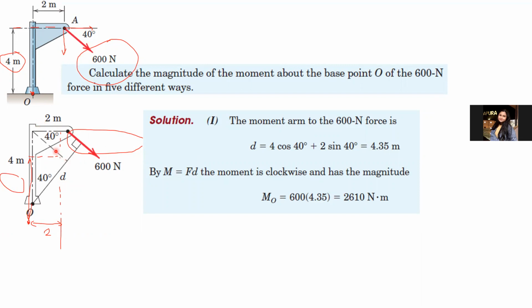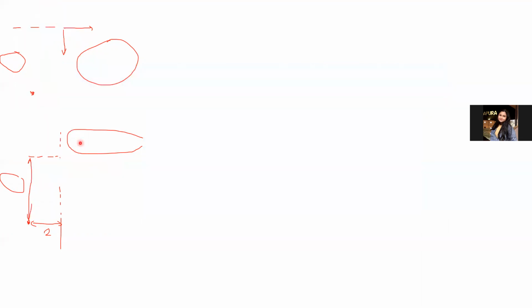So sometimes it is much more difficult to directly find the perpendicular distance of the original force, and most of the time it is easier to divide the force into its components and find the perpendicular distance of each component.